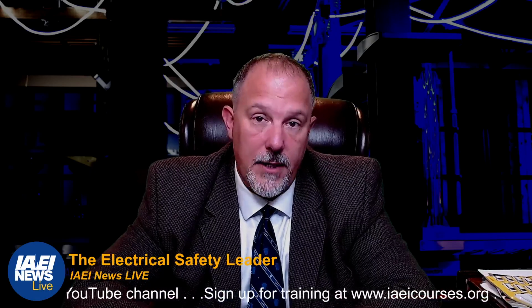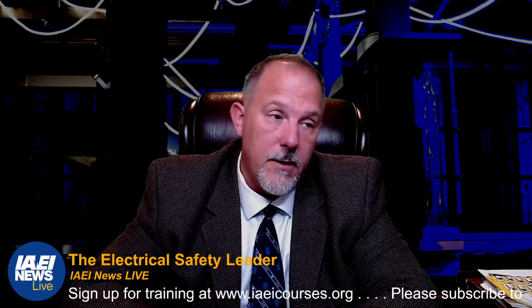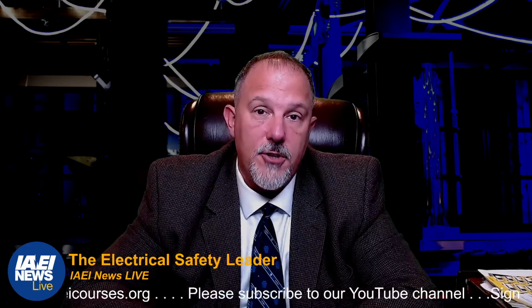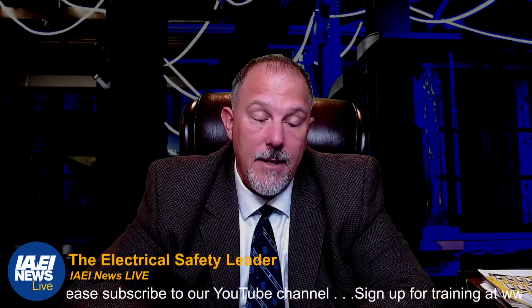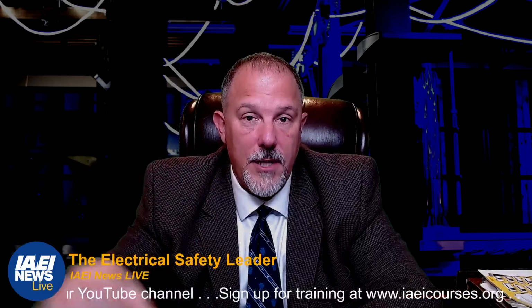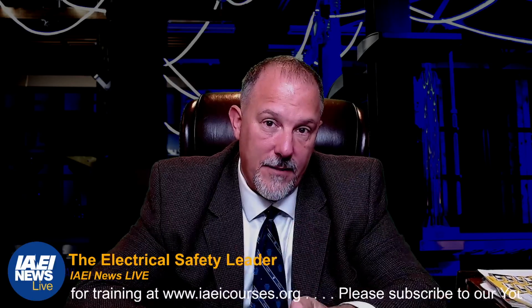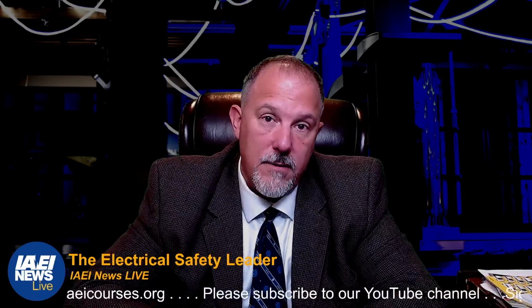80% rated is what it is. You're using a little bit larger of a conductor for the current, the load that you're serving. It's a continuous load. That larger conductor helps reduce the heat and get the heat out of that enclosure, and we test that way. Unless it's 100% rated, which means the breaker, the fusible switch, the enclosure size, the bus structure that's inside that enclosure, all of that makes a difference. So hopefully you learned a little bit more about that topic.